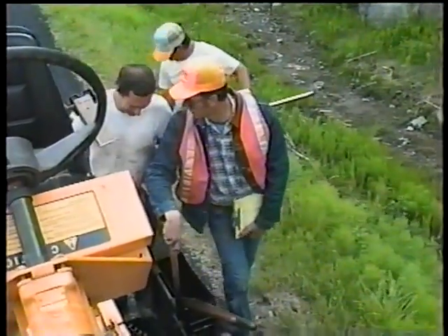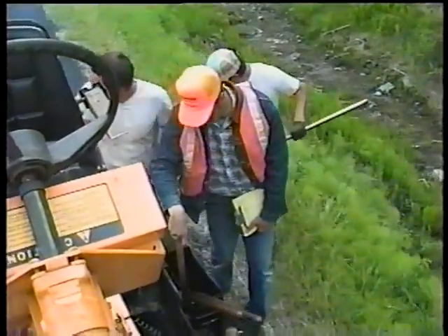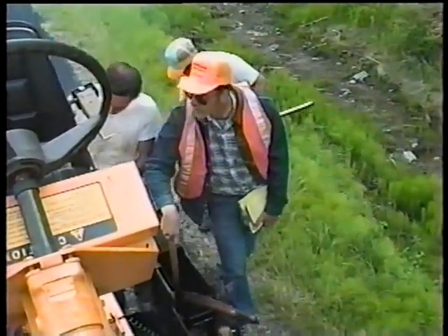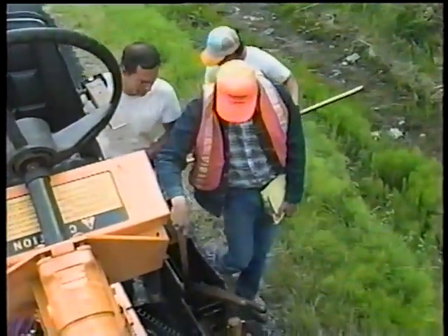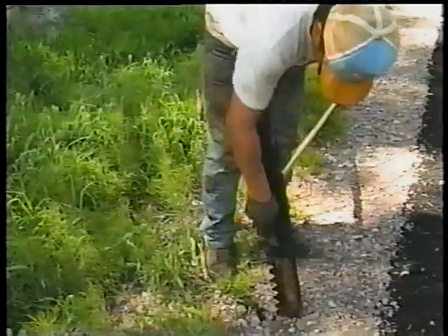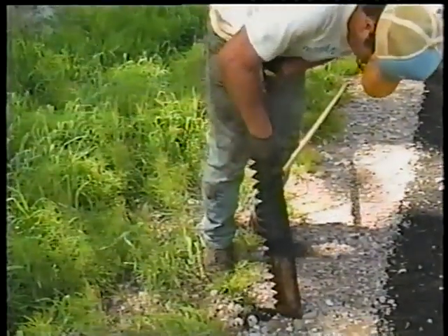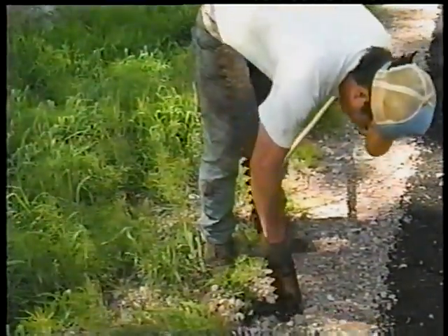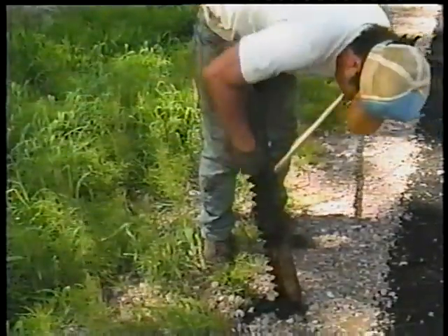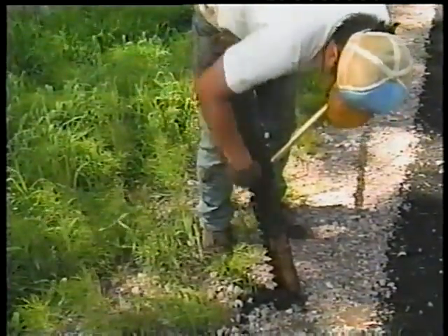Just one more point about hand tools. Most contractors store them in containers filled with diesel fuel. That's perfectly acceptable, as long as the fuel isn't spilled on the mat. While the hand tools are in use, however, they should be cleaned with a putty knife, not with the diesel fuel. And they shouldn't be cleaned by scraping them off on any part of the laydown machine either.